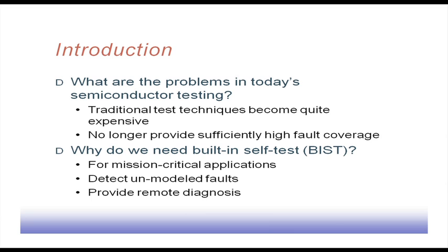The third problem is to provide remote diagnosis. As I was telling, many times the system may not be accessible. The environment may be such that it is not possible to access that system, but still we need to check the correctness of the system. For this type of application we need remote diagnosis, and built-in self-test is going to help us, where the test pattern is generated in the circuit itself, and the responses are also analyzed along with the circuit.